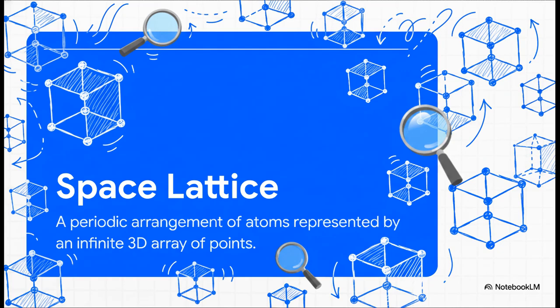So the crucial point here is that we have reached the absolute foundational level of our journey. Zooming in past the integrated circuit, past the graded PN junction, we finally arrive at the underlying atomic geometry of that flawless single crystal. And we need to establish the vocabulary of this atomic realm. We mathematically represent this perfect order using a space lattice. Take a moment to really consider what this represents. An infinite three-dimensional array of points, where each point defines the exact location of an atom or a specific group of atoms. The space lattice isn't just an abstract grid. It is the rigid mathematical backbone that ensures electrons behave predictably across billions of repetitions in a silicon wafer.